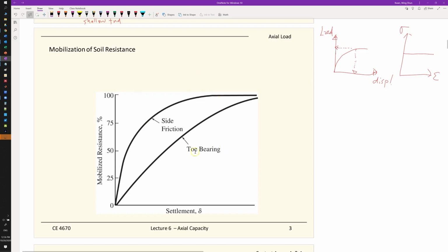So a typical response is that the soil strength you get has a displacement dependence. If you do more complex modeling, out of the scope of this class, like finite element programs or more advanced 2D or 3D modeling, you will input the stress strain response of the soil elements in the software. But in a more analytical approach, where you use a single formula to calculate the overall resistance of soils, like what we'll be doing next, we account for factors, either factor of safety or correction factors, like the alpha method or the beta method we talk about later.